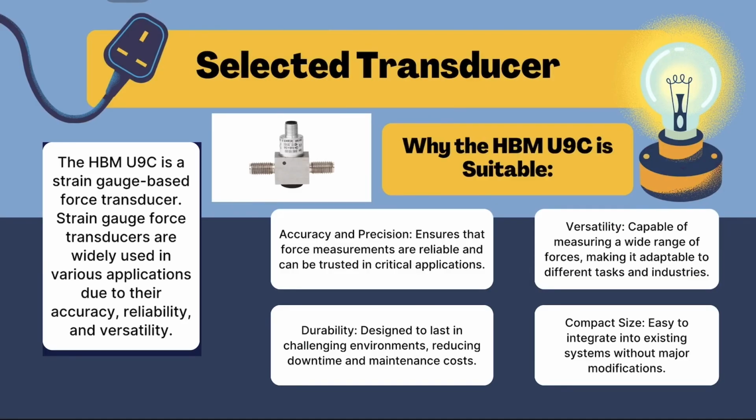So moving on, this is our selected transducer, which is the HBM U9C. The HBM U9C is a strain gauge based force transducer, which is very applicable in steel tube bending. Strain gauge force transducers are widely used in various applications, and they are very accurate, reliable, and versatile.